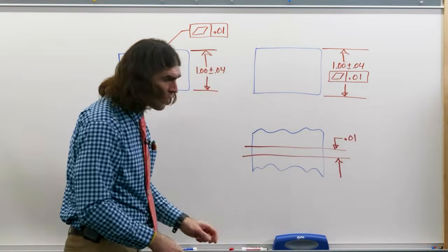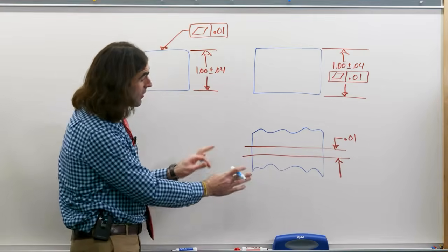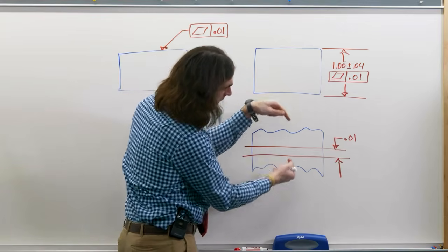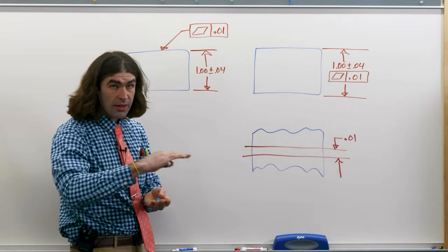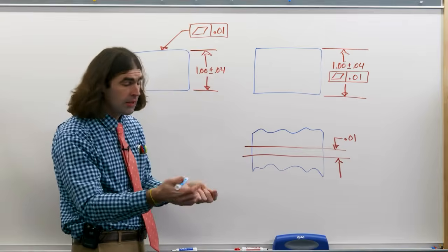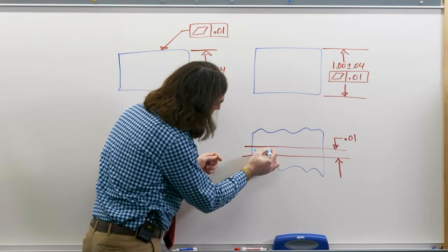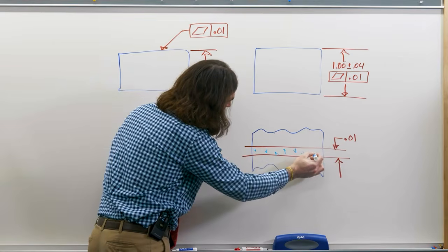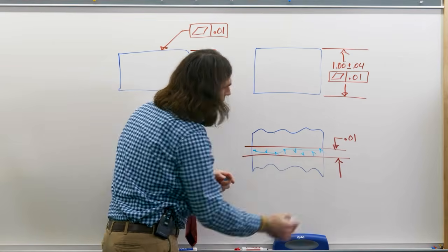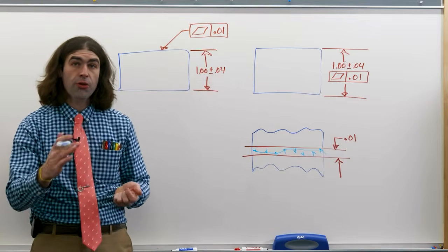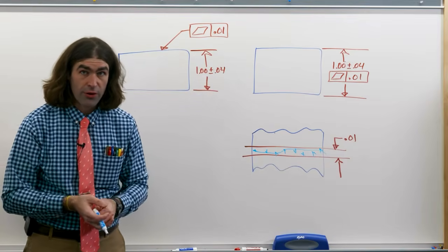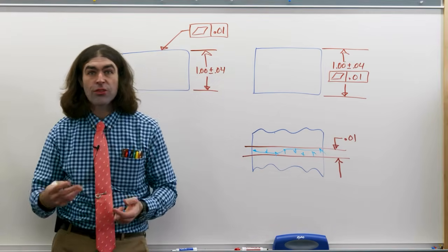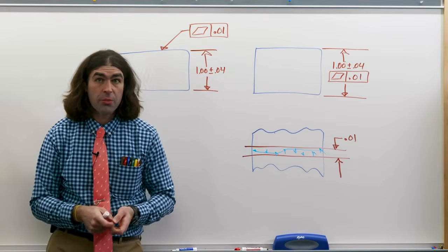So what that looks like in practice, if we take an imperfect part and we measure each 2 points on the outside through the whole length and depth of the part. Remember, it's a 3D thing. We're just going to find the middle of each of these points, right? So kind of finding the median of the surfaces of the part, the opposing surfaces. Those points must lie within these 2 parallel planes in the middle of the part.